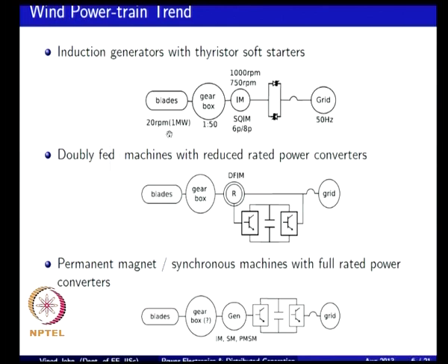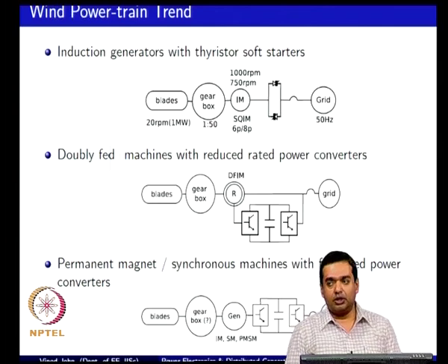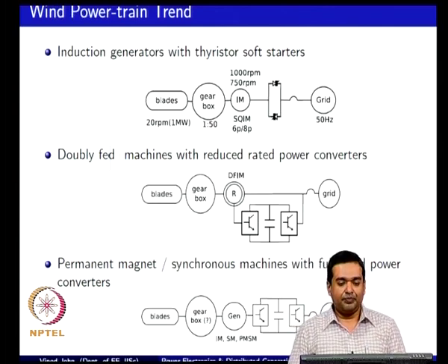And when you talk about 20 rpm, it means that in a minute you have 20 rotations. So, for one rotation it takes 3 seconds for the blade to go around, which appears slow, but because the dimension of the blade is really large, of the order of 50, 70 meters, etc., the tip speed is actually quite large, even with a slow rotational speed of the blade.